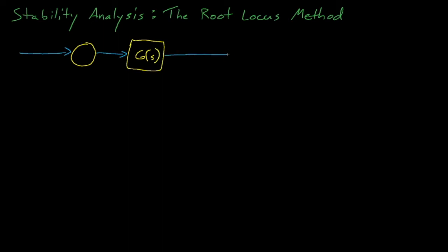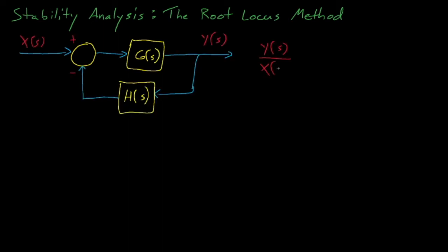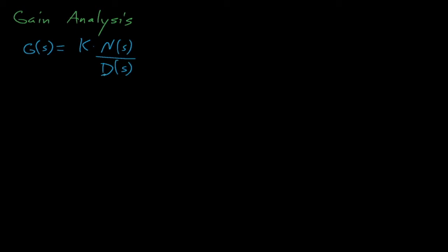Recalling the standard form for control systems transfer function, we are frequently interested in understanding how the gain, or static loop sensitivity, of control elements affects a system's stability. The gain generally appears as a constant multiplier in the feed-forward element g, where g equals the gain, k, times some numerator s polynomial divided by some denominator s polynomial. The gain of a system could represent the amplification in a proportional or integral or differential control element, but it could also equal the initial power of a nuclear reactor.